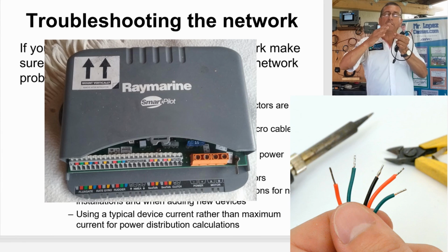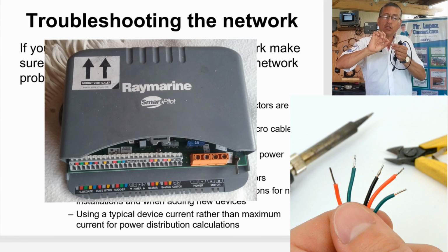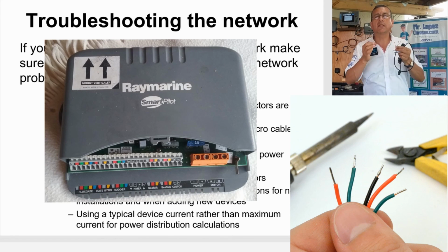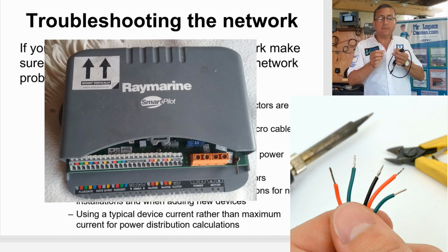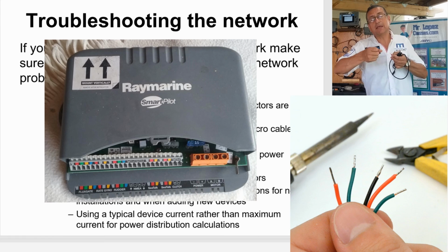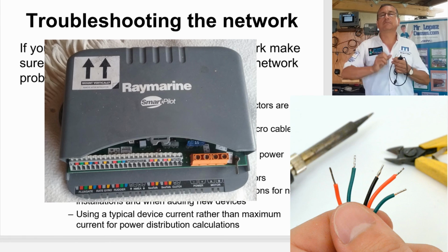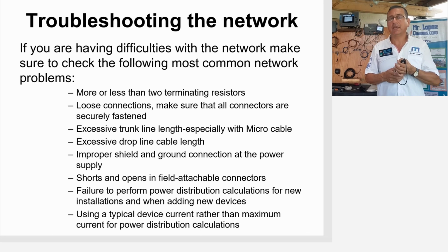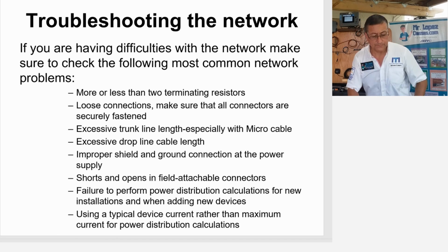When you remove the plastic in electronic cables, solder the ends. That's my recommendation. This is important. If you want to crimp a terminal, okay, remove the plastic, solder the end, put the terminal, crimp it, and use the heat gun with the heat shrink. Soldering is critical. It's important in marine electronic installations.